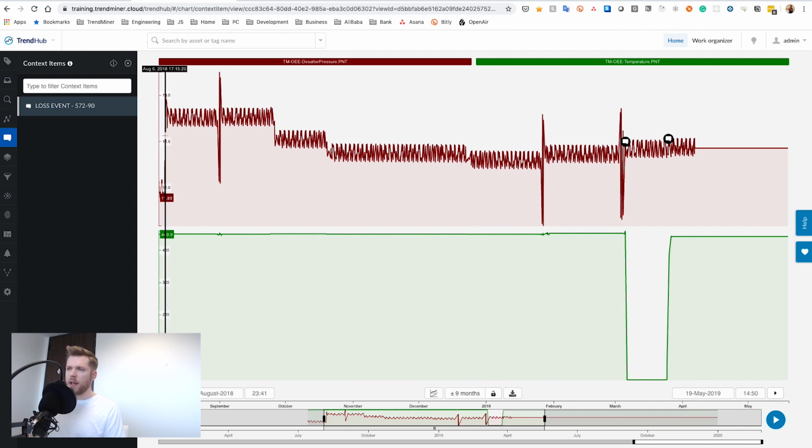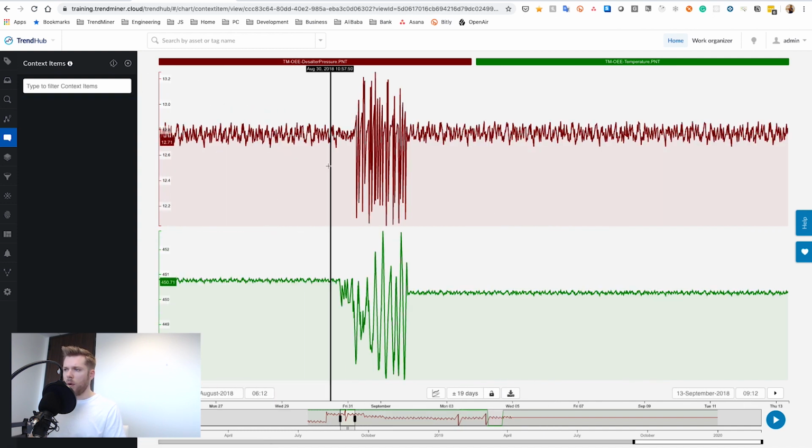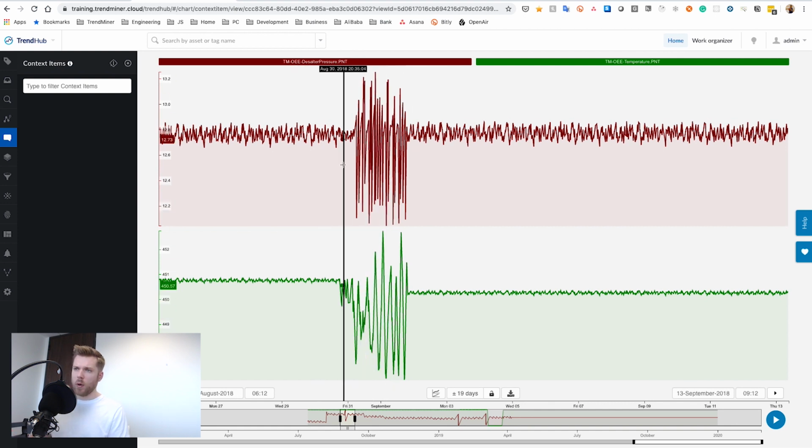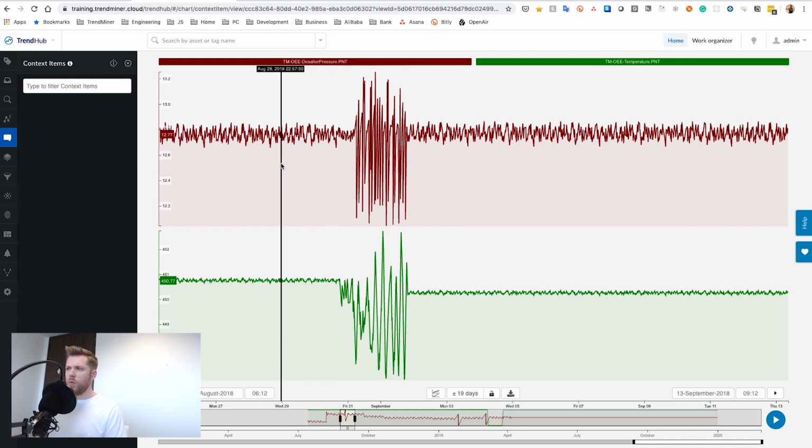The next thing I would like to do is look at these events right there, and I want to annotate where my desalter was not stable, because typically when my desalter is not stable, I'm going to have entrainment of water, and this water is going to cause all kinds of issues in my process. A couple of strategies I could follow here.